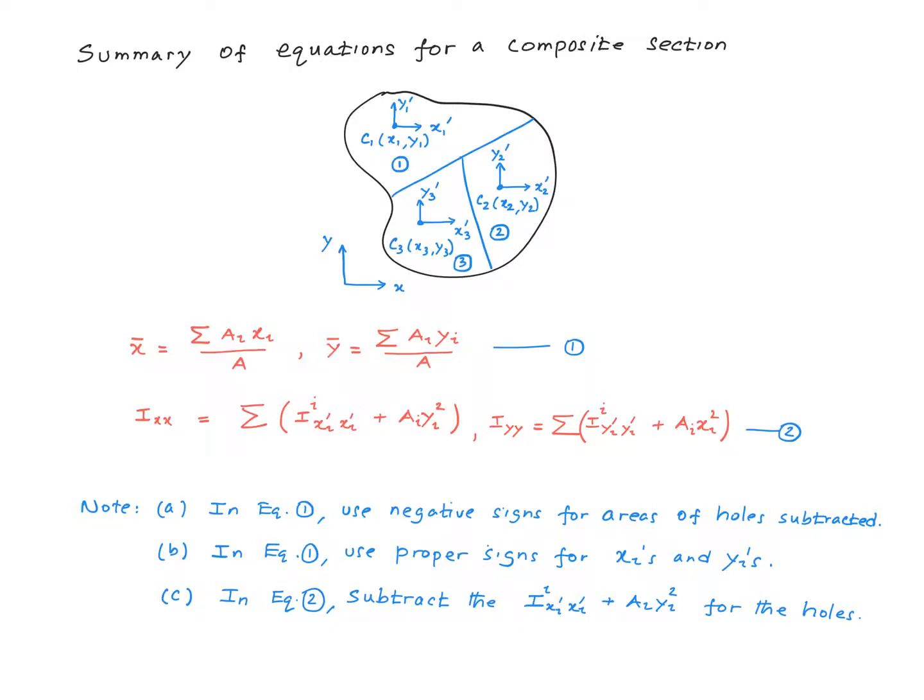For example, if I have a hollow cylinder that is being used as a beam in a certain structural arrangement, I need to find the second moment of inertia of this hollow cylindrical cross-section, right? And in that case, the area representing the hole needs to be subtracted from the overall area in order to find the properties of the cylinder.